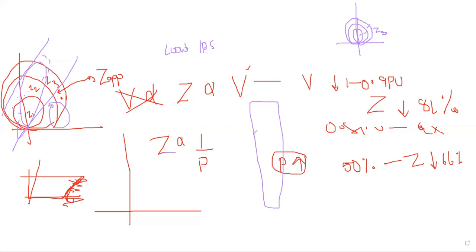When doing this calculation, I am seeing that this impedance is coming to some value, maybe at some 80 ohms or 90 ohms. Let's suppose maybe it is falling up to here. So what I will do is keep this condition that below this the relay should not operate. And again, in this direction, on the other way of the fault, this is the blinder. So in this zone, my distance protection always operates in this direction.